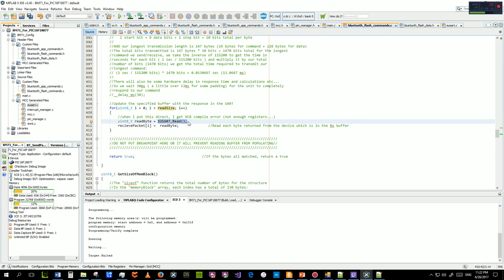This is really the only other command that you're going to have to change for your specific PIC, to read 1 character at a time from the UART. Now, your UART code should have already built into it a buffer, so you just have to call this command and it will keep collecting characters in order. You shouldn't have to worry about any of that if you use that configurator. You just have to find whatever your command is called and make sure you're using that read command.